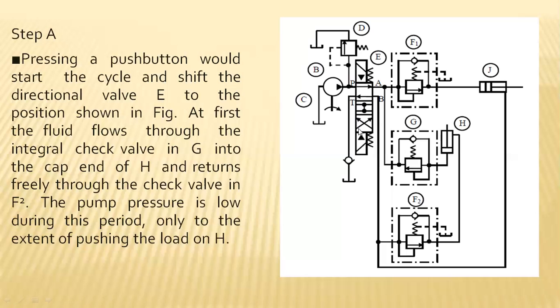So this is the directional control valve which is operated with solenoid control, spring return, hydraulic based. There are four ports, three positions, a 4 by 3 way directional control valve which is operated with a solenoid, spring return on double ends. So before this DCV, whatever the system is with respect to our circuit design, that is called the input system.